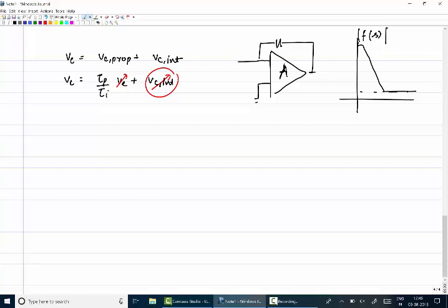So all this thing, whichever I am talking about, this is with respect to the pull-in range, lock-in range, whatever we will define. We are defining it for one particular type of PLL, and you can define it for others also. It will change depending on what phase error detector and loop filter you are going to use. Phase error saturates means if the phase error becomes, let's say, pi by 2, the phase error detector is giving you the maximum value or the minimum value, right? Whatever it gets saturated to one side, and the proportional and the integral path are trying to recover the frequency, but they are not able to recover the frequency.